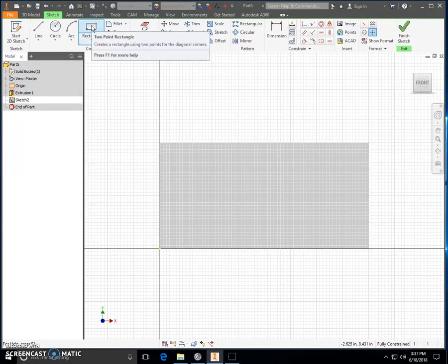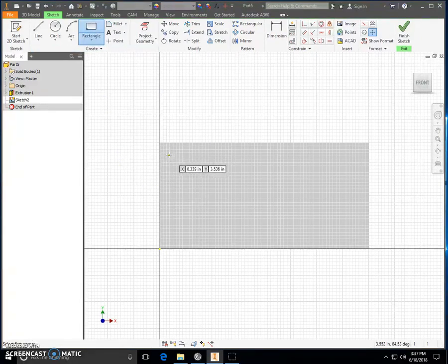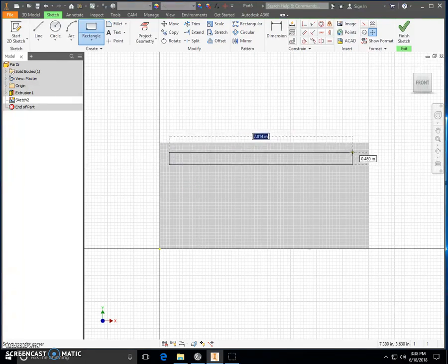Then I'm going to start with a rectangle. This is for my pencil. I'm going to click rectangle tool. Now I'm going to be on my workpiece. I want to start inside the gray area. I want to put my mouse over on the left hand side, click, and stretch out a rectangle. My horizontal dimension, highlighted blue, is going to get changed to 7.5 inches. Press the tab key on the keyboard. My vertical dimension is going to get changed to 0.437. Sorry, I misspoke earlier, 0.437 is what you're changing that to. And then press enter on the keyboard.